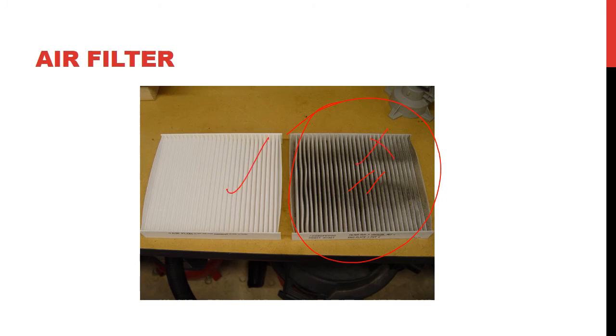Some of those filters are very inexpensive. Make sure also the direction of the filter is put in the right way. There's usually an arrow here that tells you which side should go towards the fan and which side should go toward the duct.